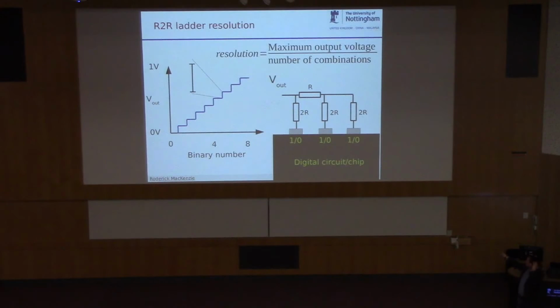So if you've got 3 pins, you can count up with binary. There's 1, 2, 4. So 4 plus 2 plus 1 is 7, plus 0 is 8. So you can count up to 8 here. So you've got eight levels of precision, which means if you're trying to generate a voltage between 0 and 1 volts, you can select your voltage in steps of 1 divided by 8.